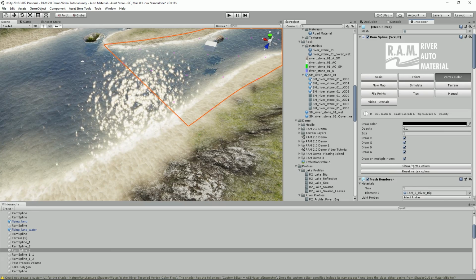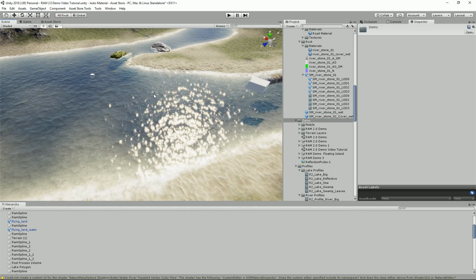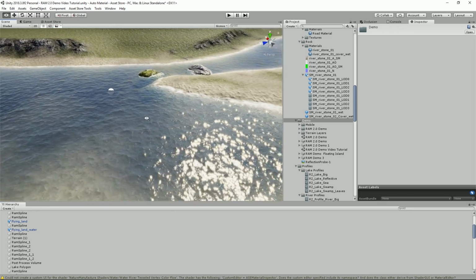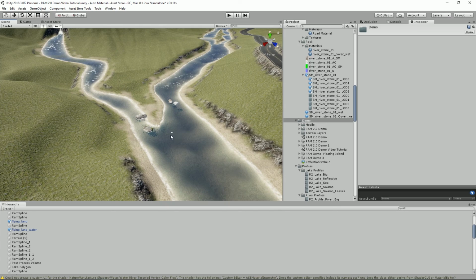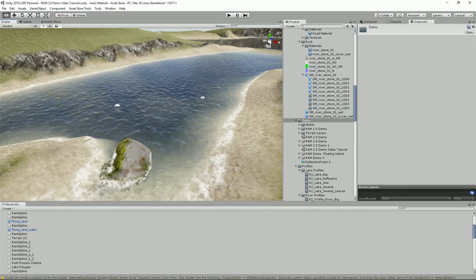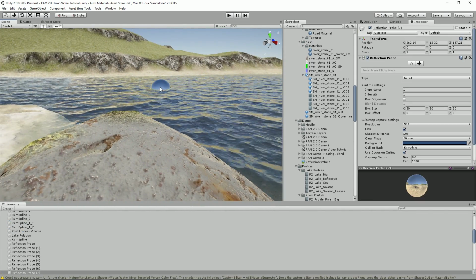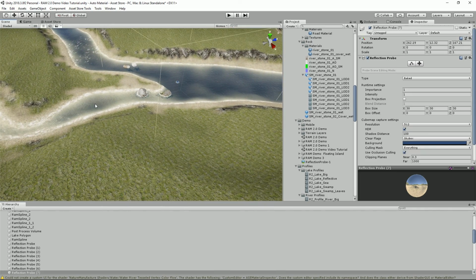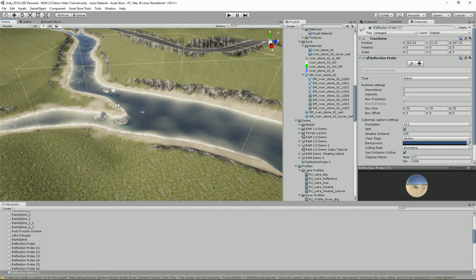You have to keep the same automatic Flowmap values, the same Flowmap noises, because if you don't keep an eye on it, you will get a bad result. You will get gaps, and that's why it's the most difficult connection. When you think about reflection, it also gets a bit difficult, because when you use alpha blending reverse, you also alpha blend reflections.